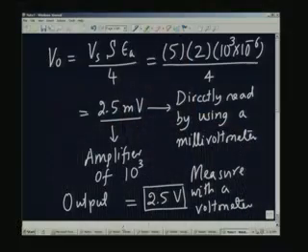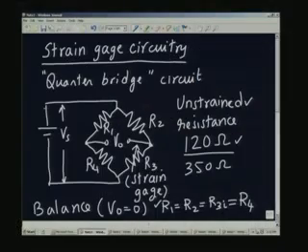And if you look at the circuit we are using, there will be a current passing through this, and the current will branch out into two portions. One current will go here and one other current will go through that, and therefore, each one of these resistances R1, R2, R4, R3 is going to carry a current. And if these currents are all the same, and if all of them have the same temperature coefficient of resistance, probably they will all cancel out, but it is not necessary that it will happen.